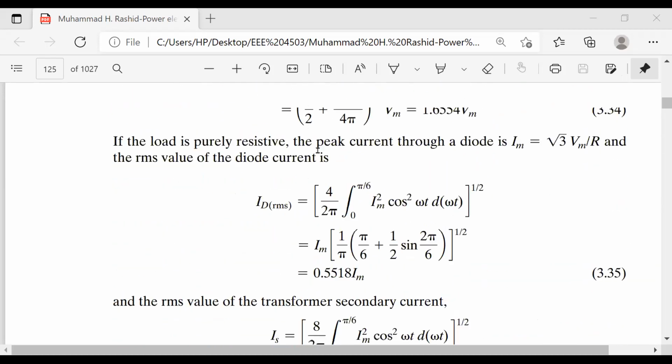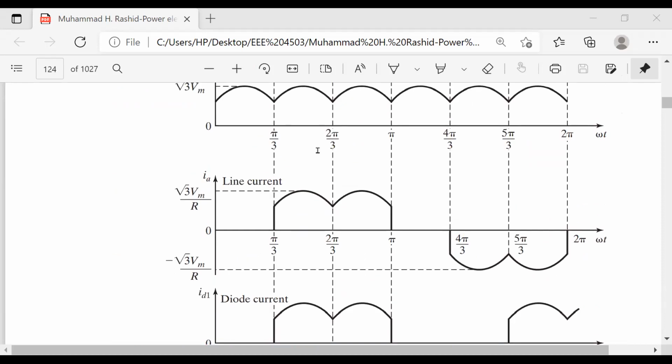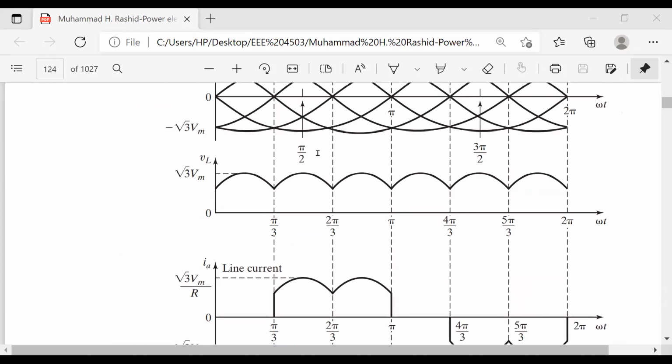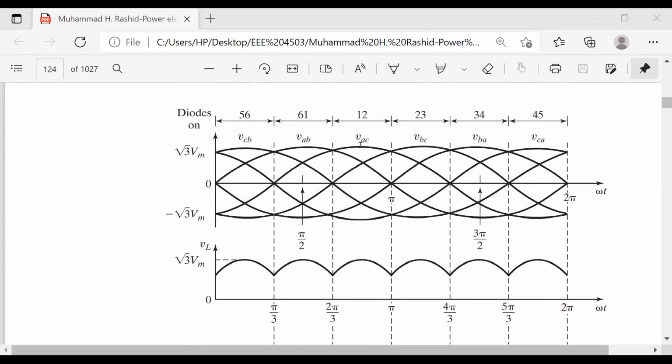what about the current? If we think about the armature current, phase A current. So phase A current, where the phase A is connected, we have to find out, right? Now phase A, look here, this is your A. Here also there is an A. So with this one, only this current and this current will contribute to your phase A. That is why we write it this way.